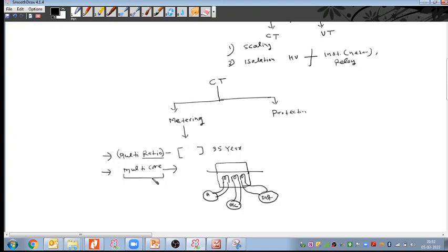And when we talk about CT sizing, basically we are not doing CT sizing, we are doing core sizing. We are doing this core sizing because each core has different applications. So for each core we have to do the selection and the sizing calculation or the rating calculations. This core is altogether different from this core, so we can define or manufacture each core with different characteristics.